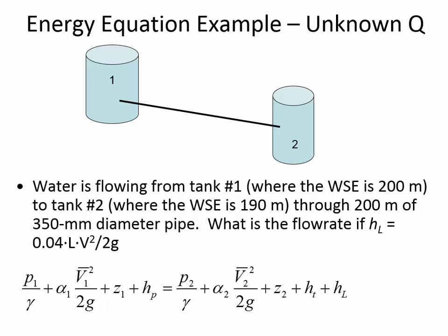And we're given an equation here that defines the head loss. We're given the equation that head loss can be calculated as 0.04 LV squared divided by 2g.